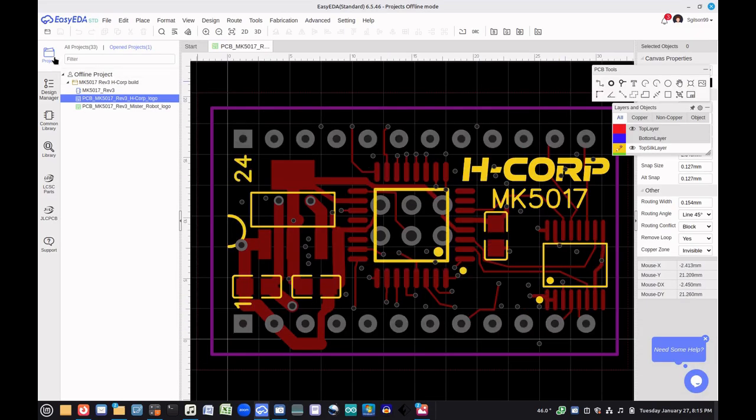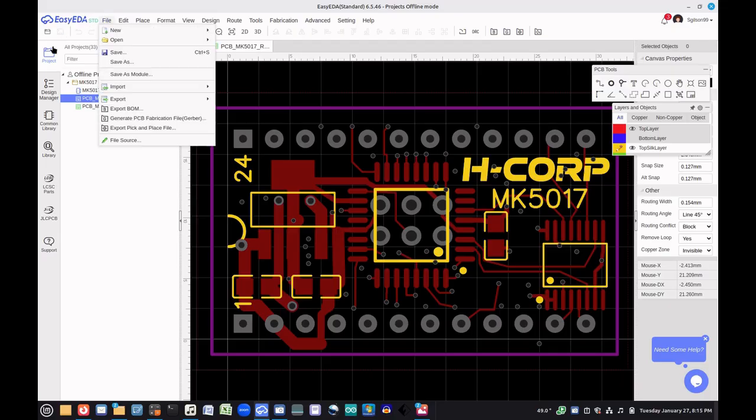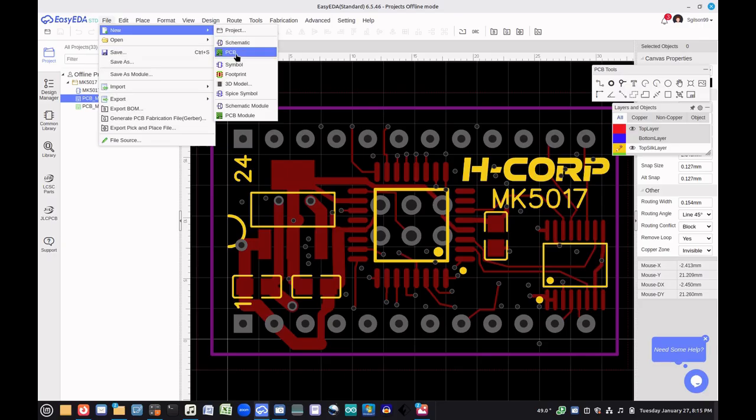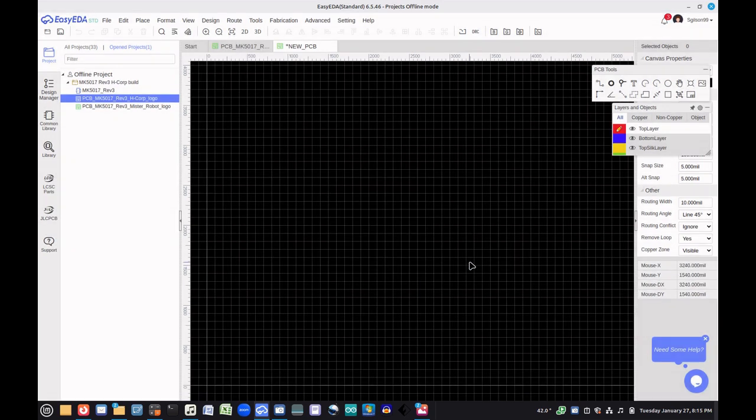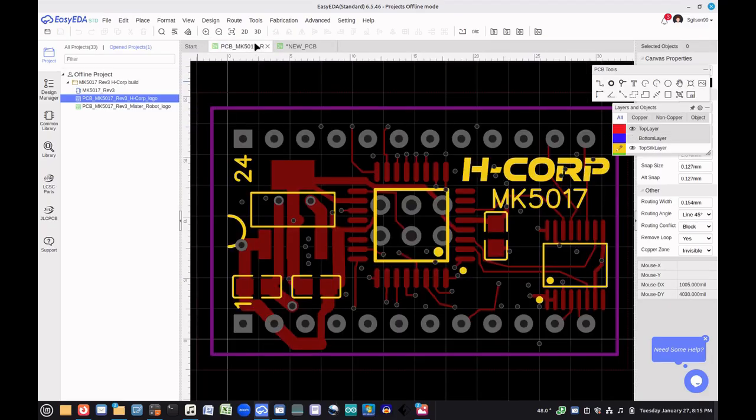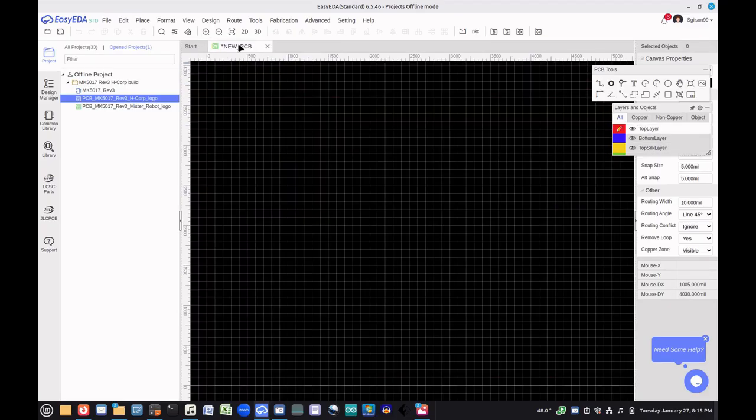We're going to go back and do a File, New PC Board. It's going to be a blank PC board. We don't need to set the dimensions. Let's just cancel out of there because it'll dimension itself. And what you do is I can close this additional one. The only thing you need open is the PC board because we're going to pull in copies of the module.